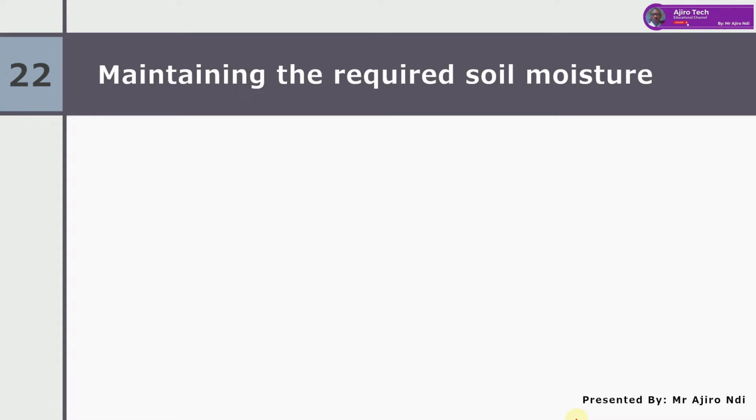It needs an ADC to change the analog moisture data to digital values the computer can understand. The computer compares the sensor data to the preset value input earlier by the user. If the level of moisture is below the preset value, it sends a signal to an actuator, which activates the sprinkler valve to open, or leave it open if it's already open. If the moisture level is above or equal to the preset value, the computer will send a signal to the actuator to close the sprinkler valve or leave it closed if it's already closed.